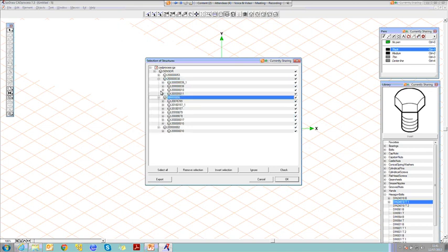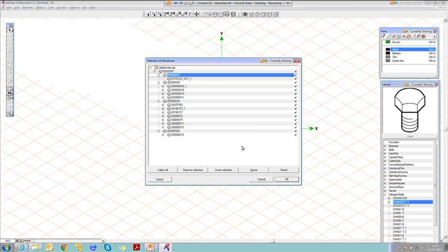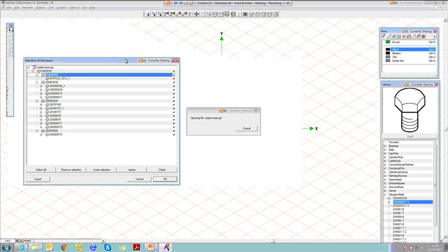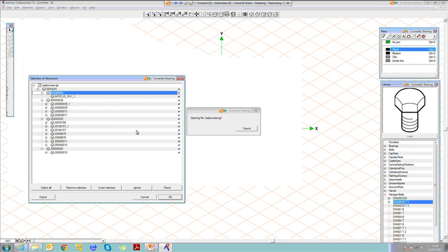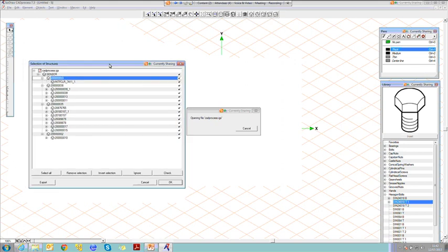This is really important because as a technical illustrator, you just need to document areas of the model a bit at a time. You don't want to have to work with the whole assembly. You could import the whole assembly all together and then spend your time sifting through all the various different parts. Or alternatively, you could work with a little bit more intelligence and select areas of the model that you want to bring in individually and say, I just want to focus on this sub-assembly, just these parts. It enables you to import the information that you want. This IGES file, IsoDraw has recognized the model tree that was used to create it.